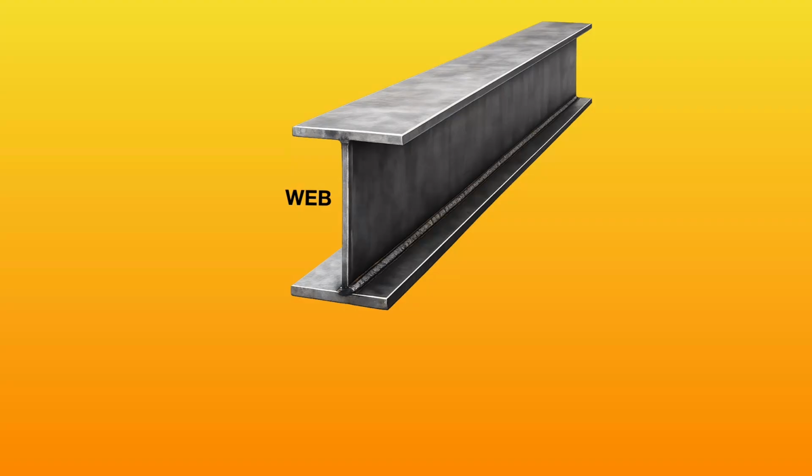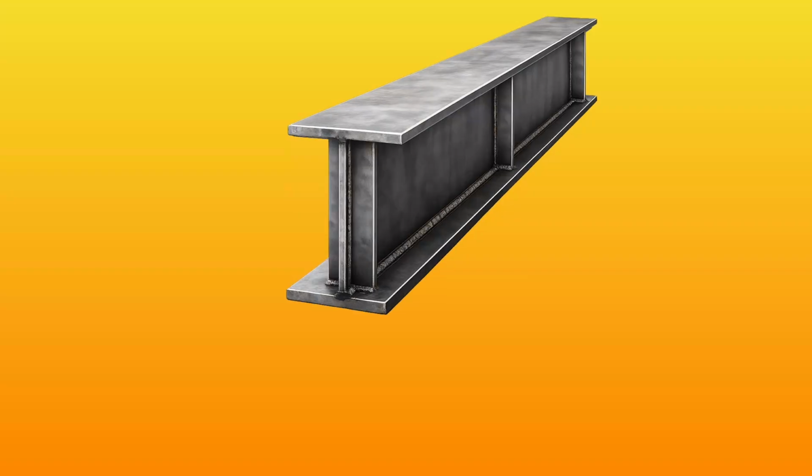Now, if we want to increase the capacity of that beam, we could thicken the web or we could deepen the web. If we make the web too tall, then it's at risk of being too slender. So what you can do, as well as thickening and increasing the height of the web, we can also strengthen it by adding stiffeners to the web.